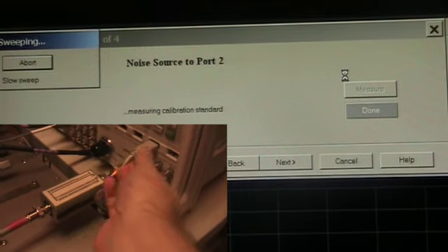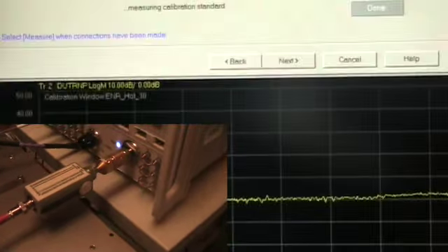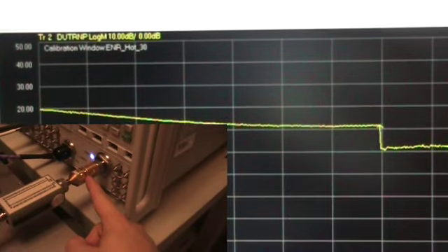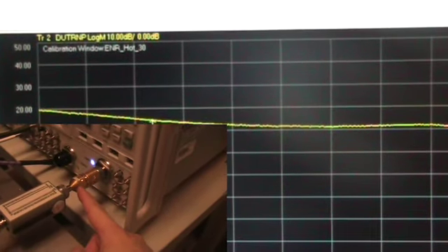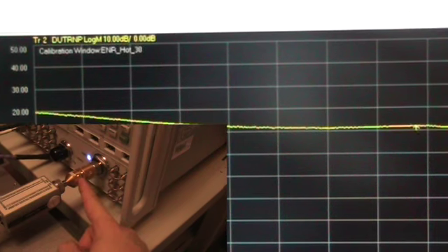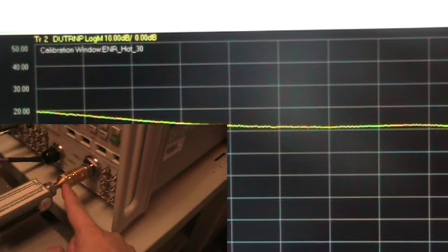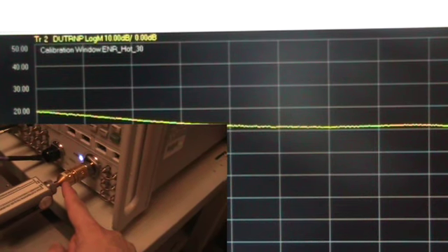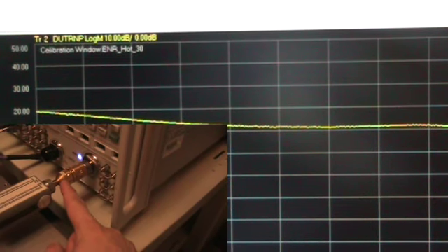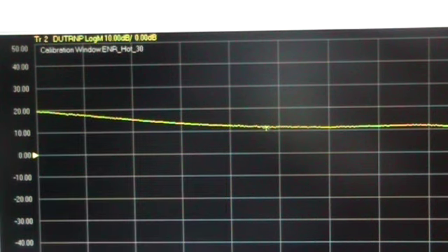Now what you see on the menu, on the windowing down below, is the system will be measuring the excess noise with the noise receiver. We'll actually perform this 3 times. Internal to the network analyzer is an LNA. The LNA can add 0, 15, or 30 dB of gain between your excess noise and the actual receiver.